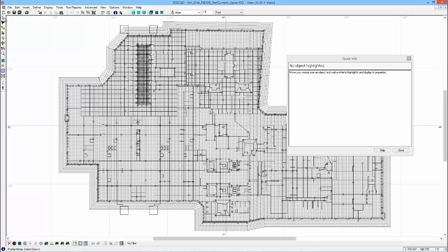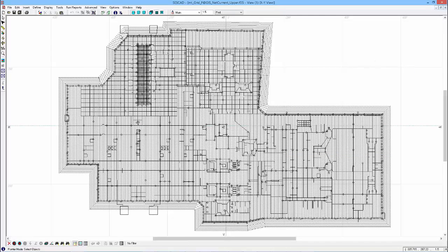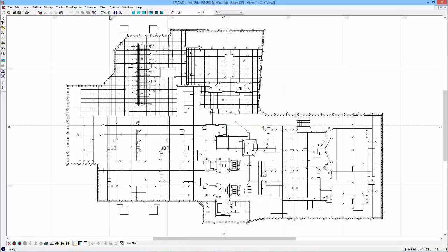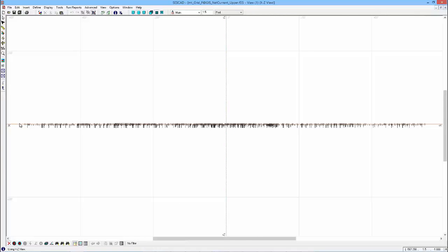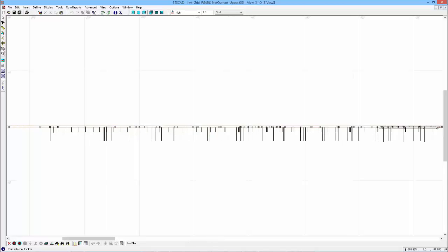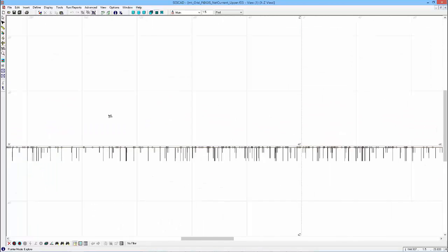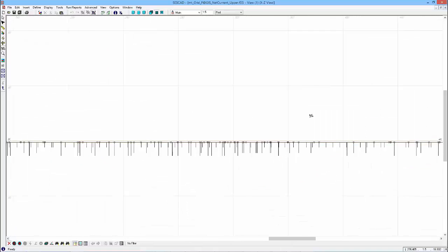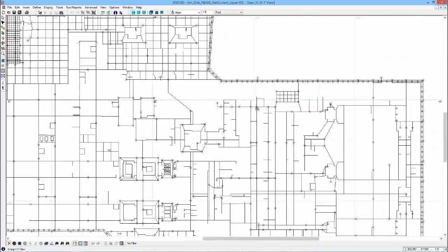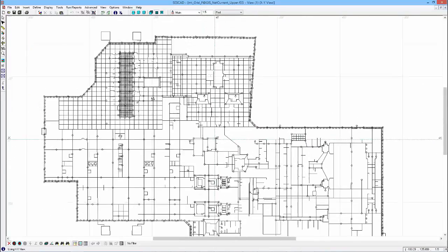To see the grid conductors better, we're going to hide the profiles display, and we can see the conductors far better now. As I mentioned before, we're only seeing above ground conductors. We can take a side view just to see that no conductors, I'm zooming in with the mouse wheel here and panning, no conductors are above grade. Let's go back to a top view and let's zoom in to the GIS building.